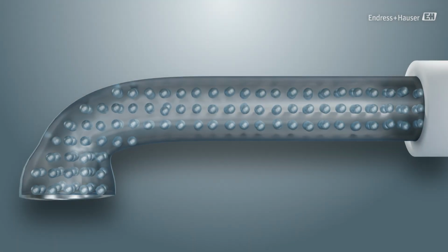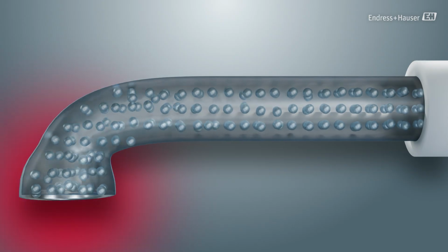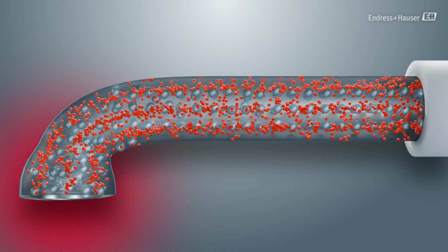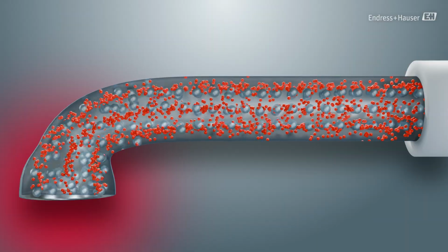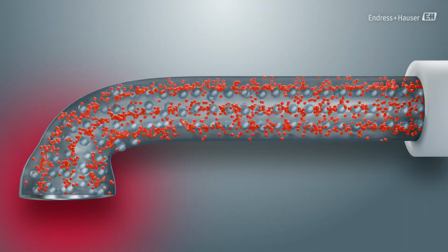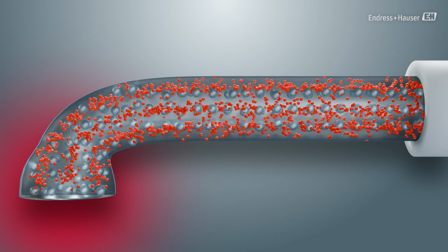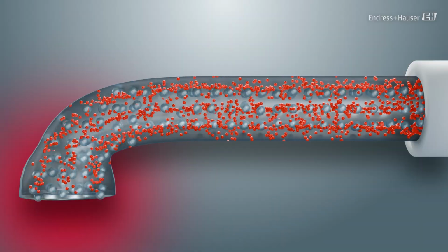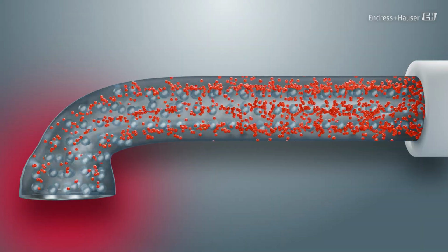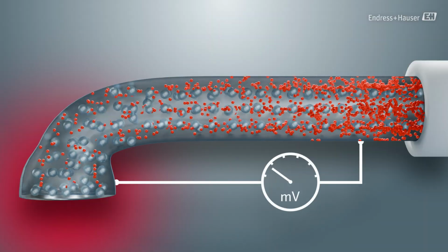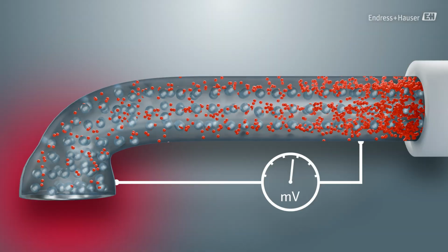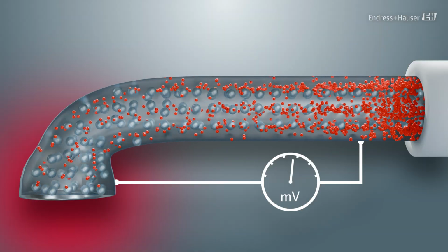When one end of a metal wire is heated, the atoms in that region begin to vibrate more intensely. These vibrations transfer thermal energy to the free electrons, causing them to move faster and more energetically than those at the cooler end. While atomic vibrations scatter electrons randomly, the hot region still holds more high-energy electrons overall. This imbalance leads to a net drift of electrons from the hot end toward the cold end of the wire. As these energetic electrons migrate, the cold end starts to accumulate negative charge, while the hot end becomes slightly positive. This creates a small voltage across the wire.